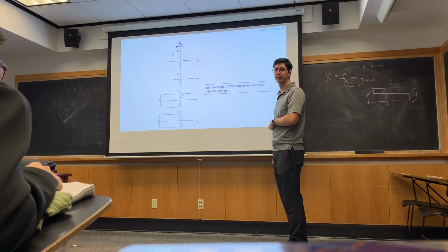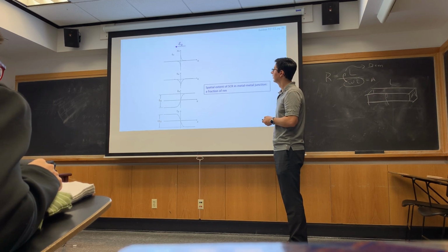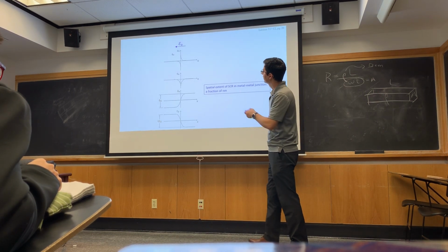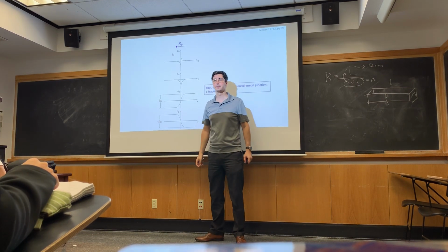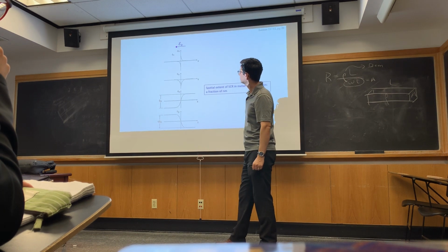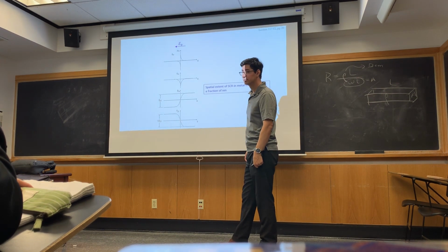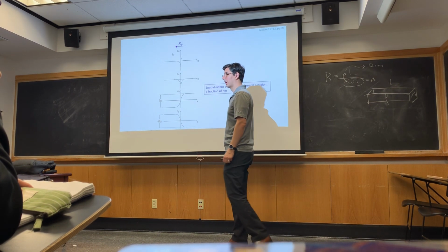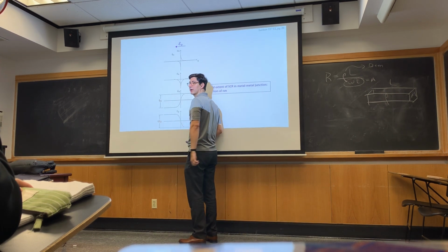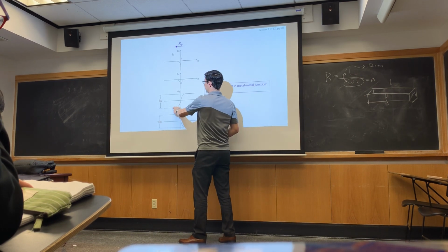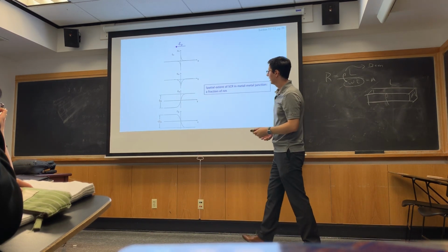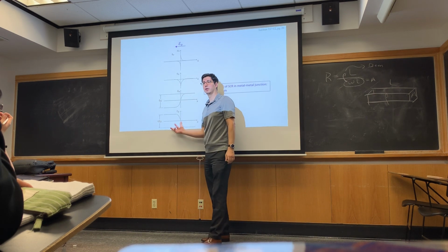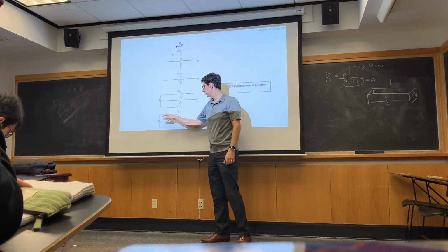I hope I said that correctly earlier, right? That electric field in this scale is negative, so we're going to see it dip down like that. Everywhere my electric field is negative, right? Here's my potential, it's the integration of my electric field with a negative in front of it. Electrostatic potential and then potential energy for an electron, right? It's going to be like this.